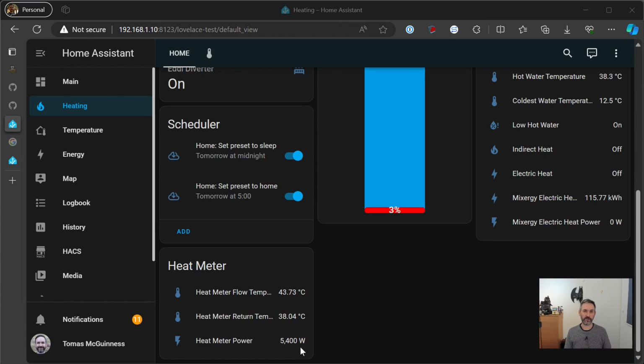And then I need to set up some kind of a cron job, or a repeating job as it were, so that the fetching of the data is done on a schedule. So we might sample that from the heat meter every 30 seconds maybe. I'm also not sure about things like the power drain. So will querying the MBus interface drain the batteries in the heat meter faster?